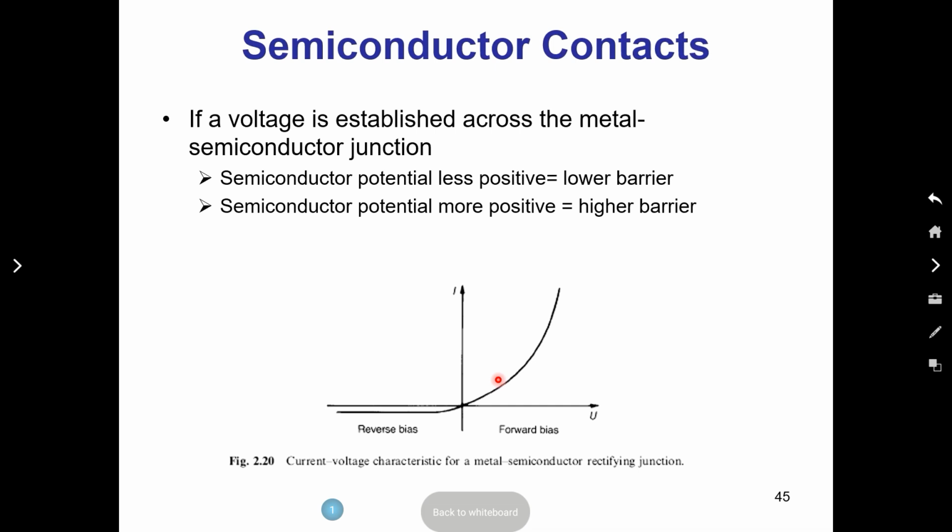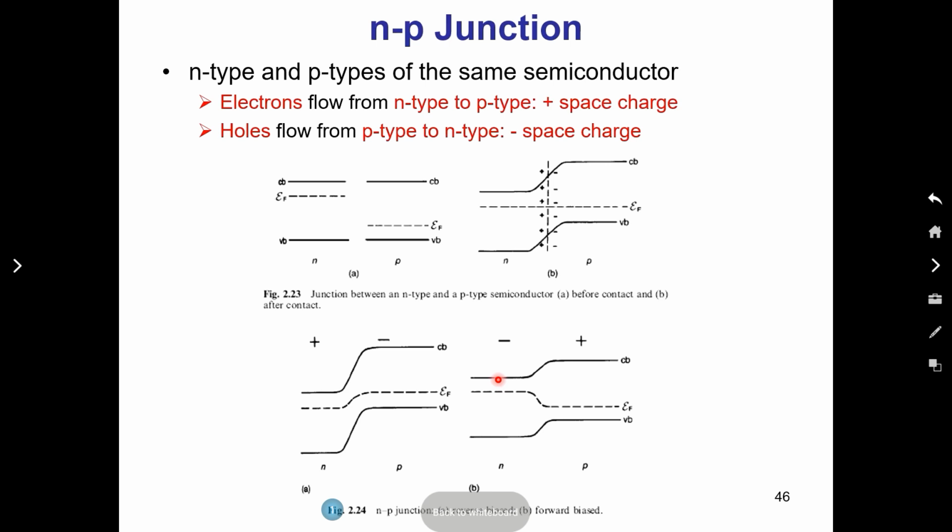So that's something where you get a charge distribution, which would be considered a localized defect. And in a semiconductor, either n-type, p-type, or even n-p, two different materials will have different work functions. And eventually, when you put the contact, they have to equilibrate.